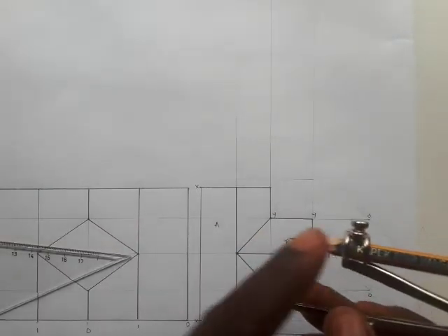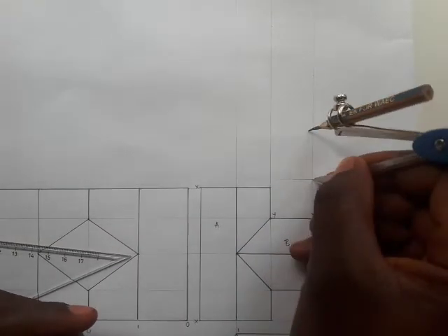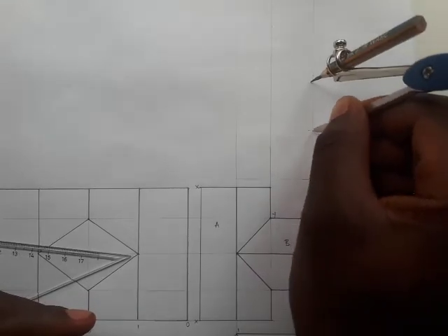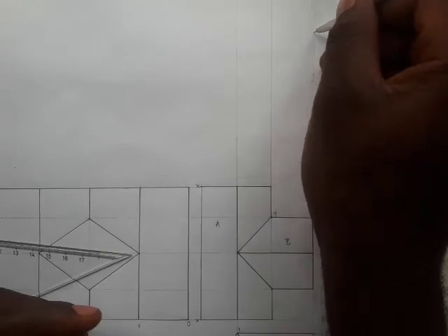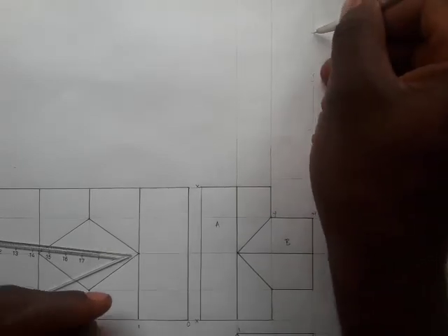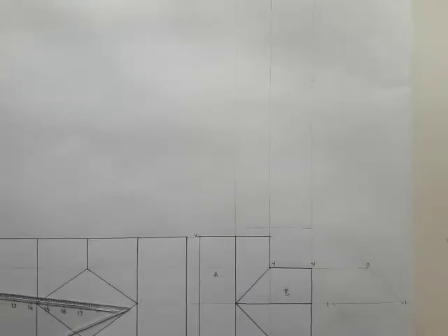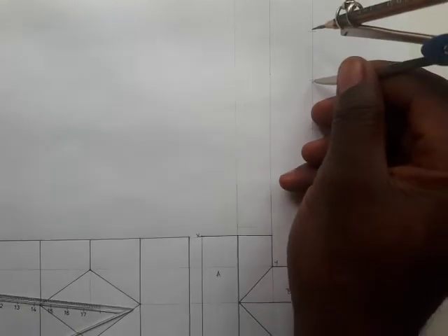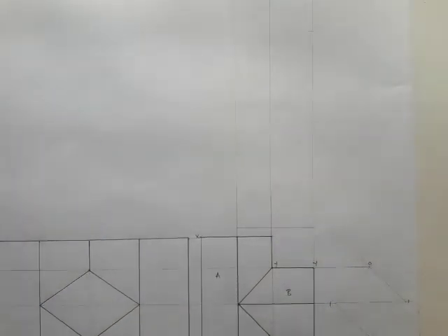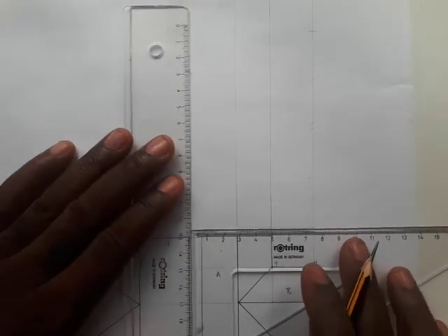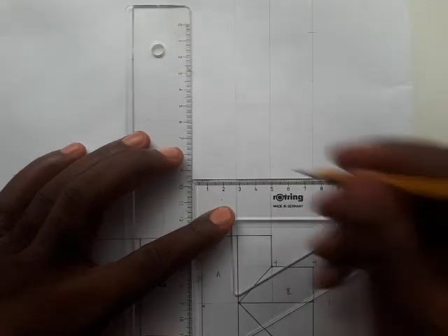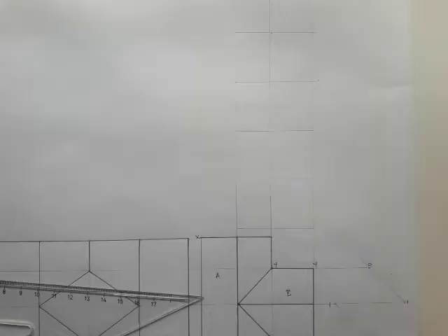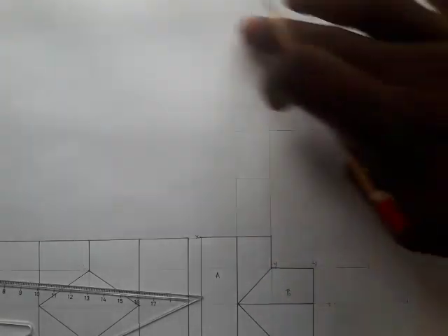So that's it. With this, step off 4 equal divisions. So that will give you 1, 2, 3, and 4. I hope you can see that. I'll just adjust. Okay, so we have the fourth one here. All right, so we'll transfer lines to all the points, thin lines. Align your set square with a horizontal. Transfer lines here. Okay, so that's it. Transfer lines there.